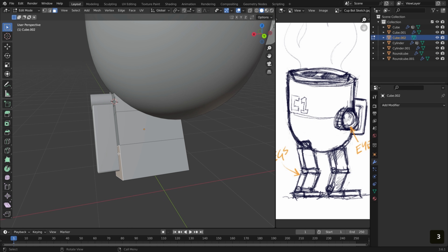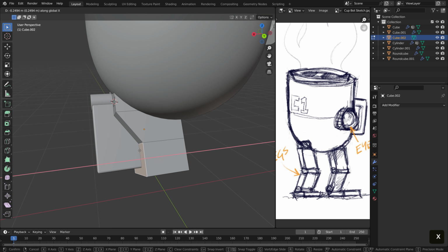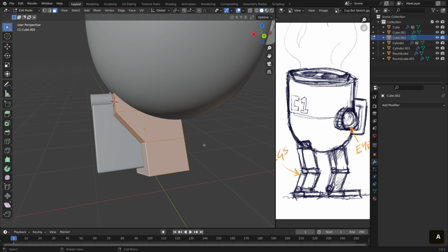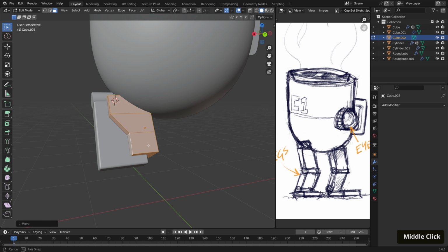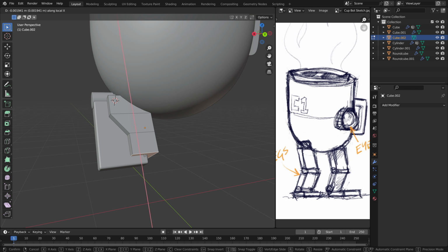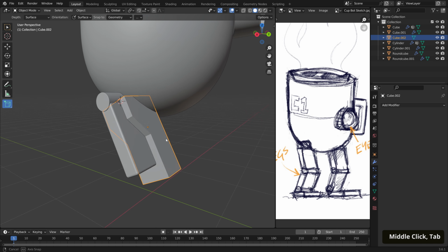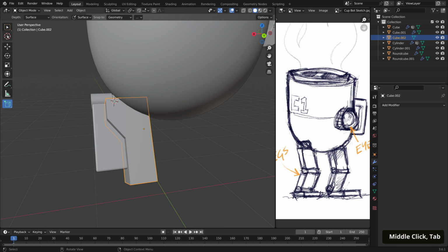And then we can hit 3 on the keyboard to select our poly mode, and then G and X to move it down until we're happy with the angle. Just going to scale everything a little bit here. Move it in. I'm just hitting X twice to move into our local coordinate space. And I think that's reasonably good.